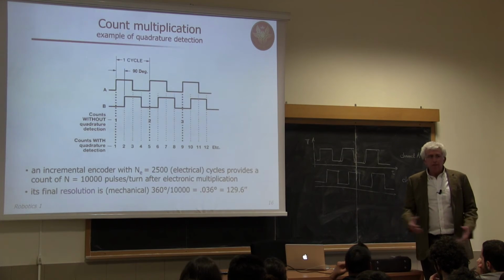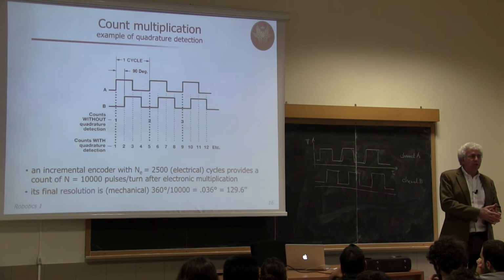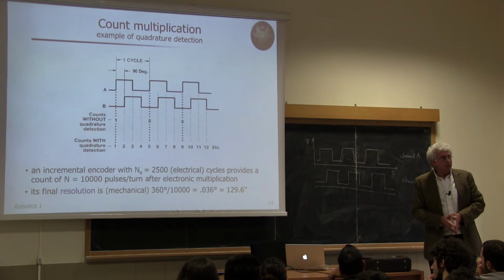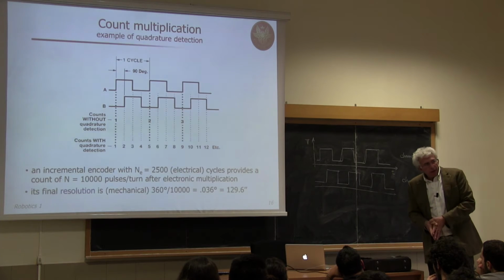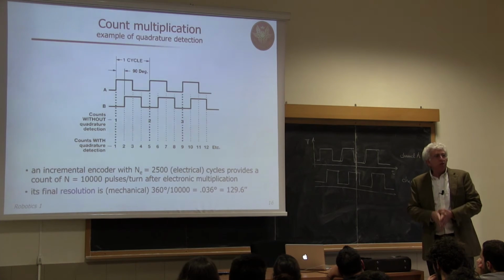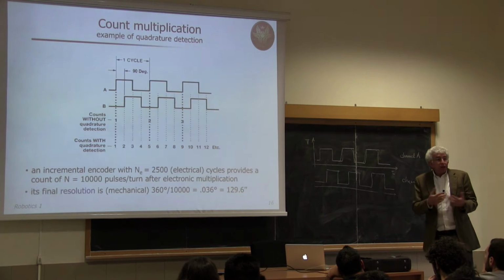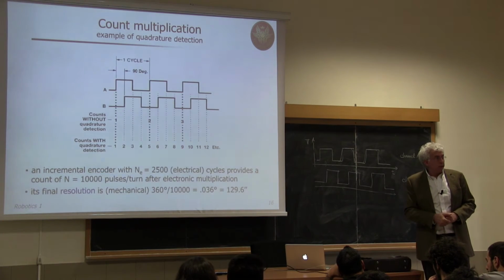So again, we have to decide if we want to have those sensors mounted before or after the reduction element. Okay? If we mount it after, we have an accurate measure of the links, which is what we really care of. But of course, we don't have this improvement of resolution related to the presence of the reduction.